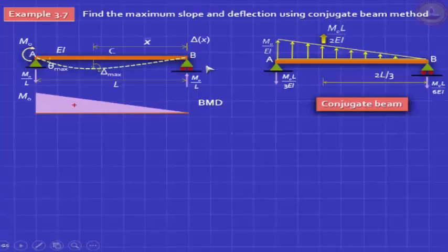Remember this, it's a golden rule. But it is true only if the beam is simply supported, only if the beam is prismatic, and only if one moment alone is applied at one end. It will be always true. So whenever you draw this also, make sure that when you draw a tangent here, this slope is roughly 2 times this slope. Easy to remember. Okay, and we've got the value. We got one answer, M naught L by 3 EI, and the other one, if you want, is M naught L by 6 EI.